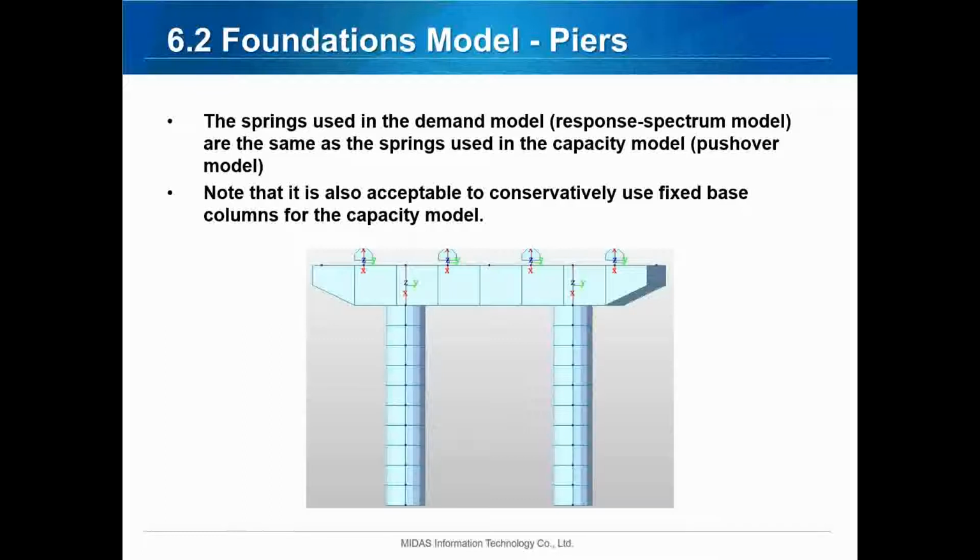I also wanted to note over here that MIDAS Civil is able to generate your springs just based on your soil properties, putting them in our model and coming up with the soil springs that way.